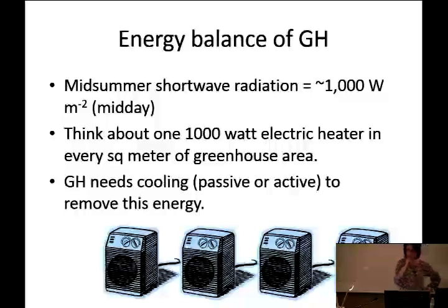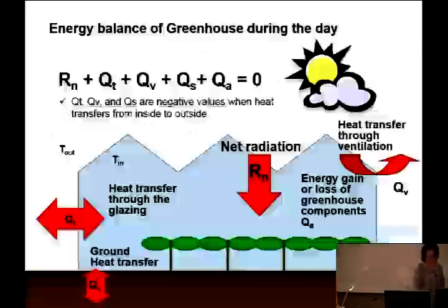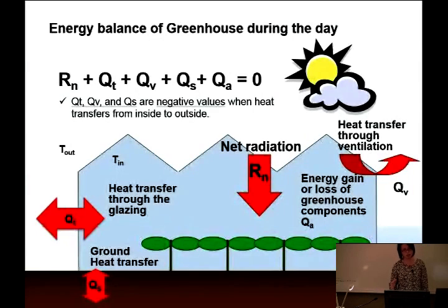So particularly that heat is too much, and most of the summertime it is too much when you apply that in a closed structure. So you need to reject the heat by either ventilation or active cooling. All right? So that's what we are doing, either ventilation or evaporative cooling, to reject or remove the heat from the system.